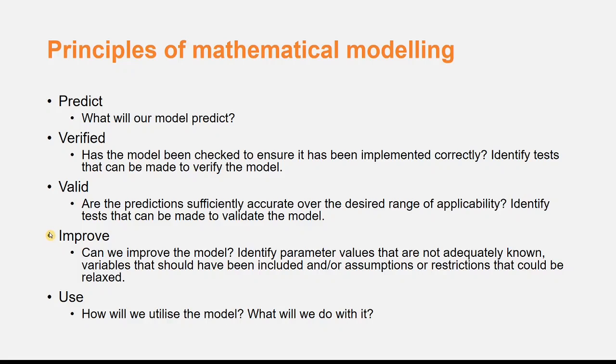Improve. Can we improve the accuracy of the model by getting better estimates of the parameters? Are there any input variables that could have been missed, or are some assumptions not valid? Use. Consider again how the model will be used. Does it need to make fast predictions, for example, for online control applications or real-time operator training? Or do you need accurate predictions and you don't mind waiting longer for a more complex model to solve?